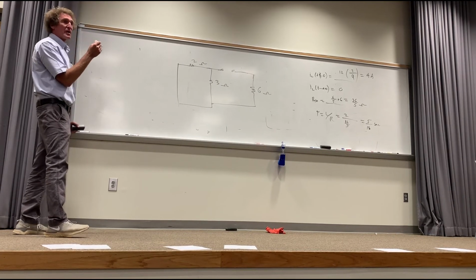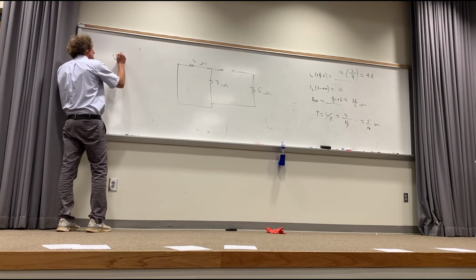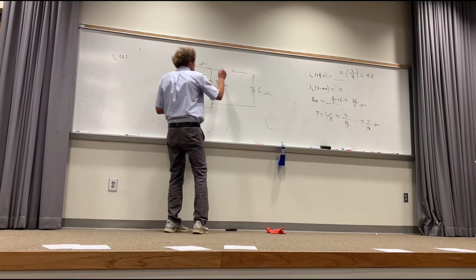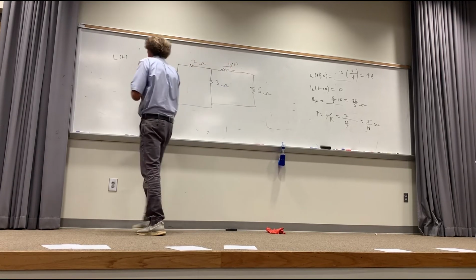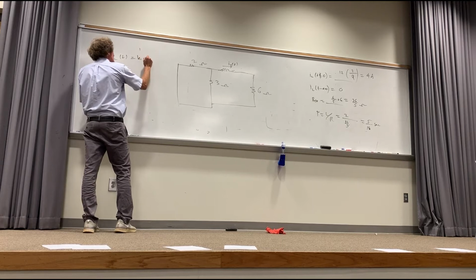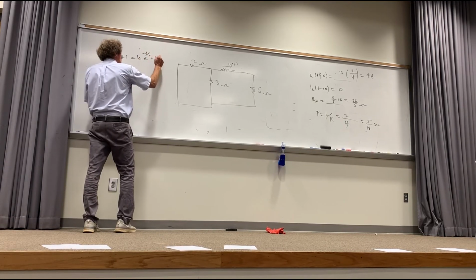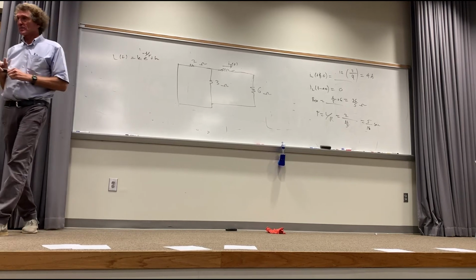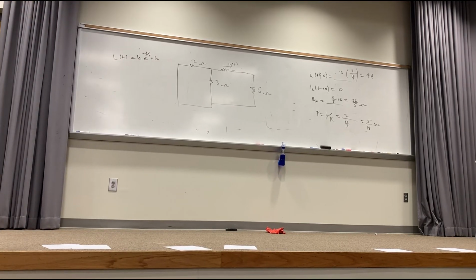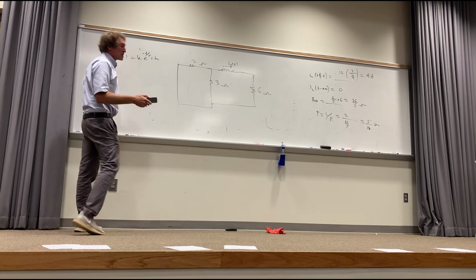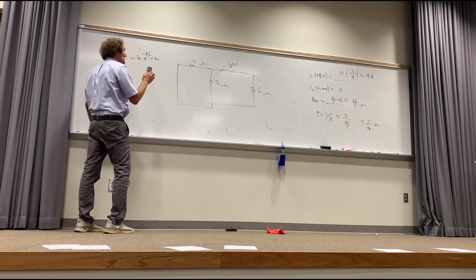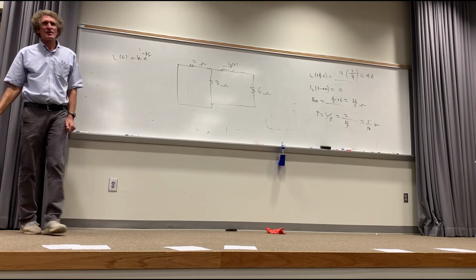Now I'm going to go ahead and write the general equation. I know that IL of t, this is my inductor, this is the current I'm getting, is going to be equal to K1 e to the minus t over tau plus K2. What is K2, class? By this time, I think you're catching it. K2 is the current as t goes to infinity, which is 0, correct? How many see that right there? If the current through the inductor is 0 as t goes to infinity, just erase K2. You don't need it.